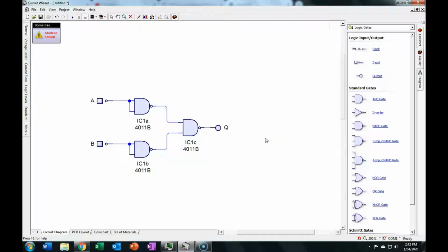and there's our circuit. In order to get it to simulate, the play button or the run button up here on the toolbar, we've got logic low, which if I hover over it, you can see that it's saying 0 volts there. That's logic low, and if I click the button there, if I hold there, it says 5 volts.